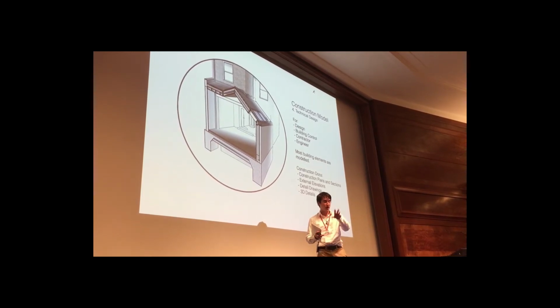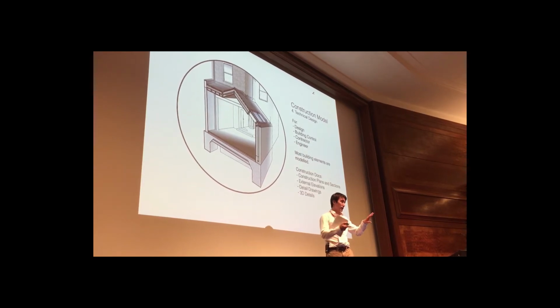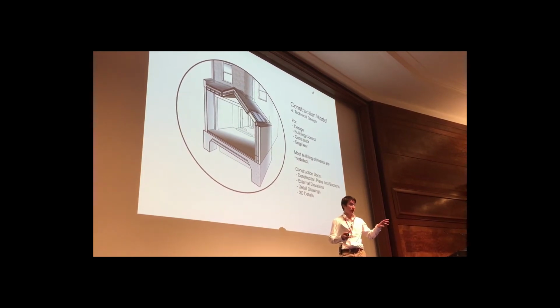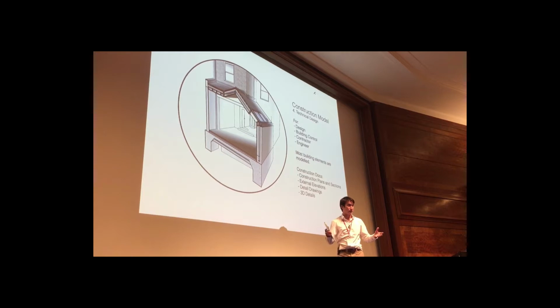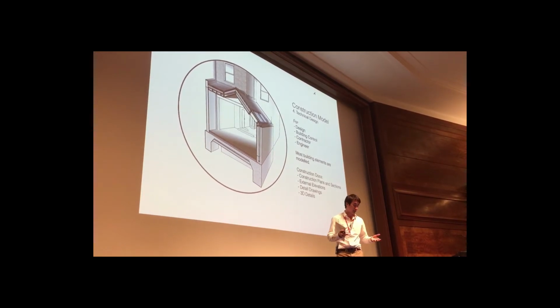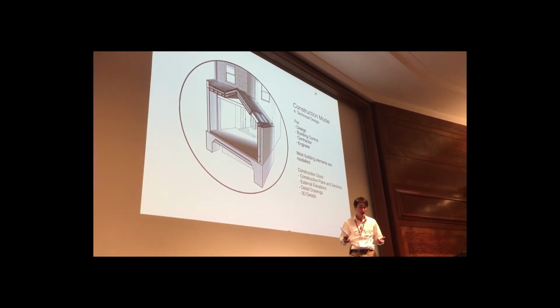I put in plants, trees, and the textures that I might apply for tiling arrangements and things like that. These all take up a lot of memory. So in my construction model, I strip all of that out. It's surprising how much of a difference that can make, just for speed purposes.